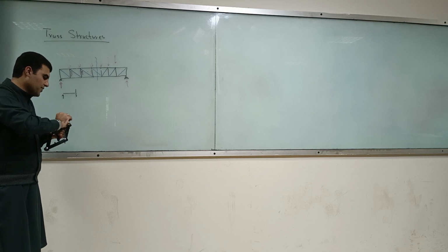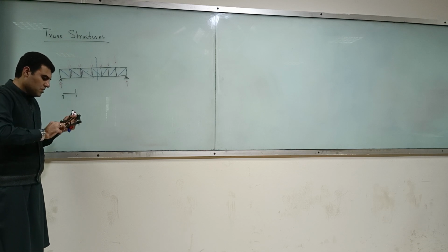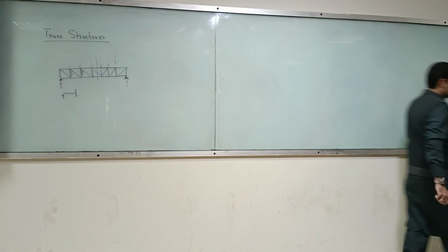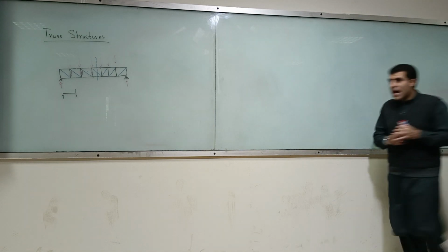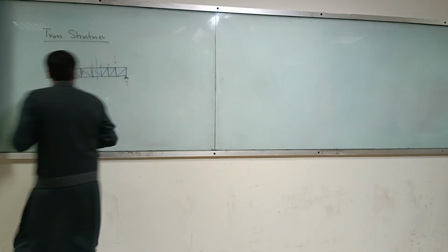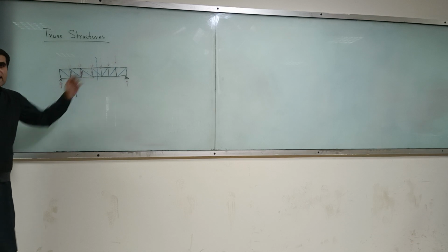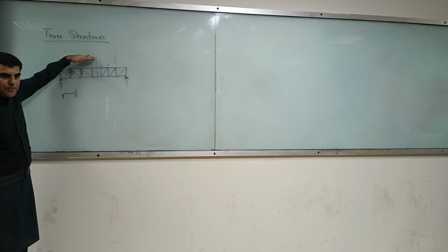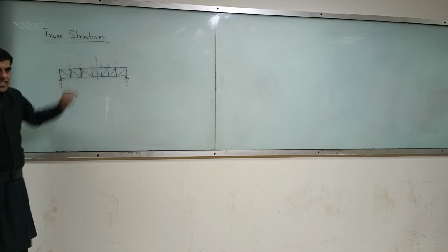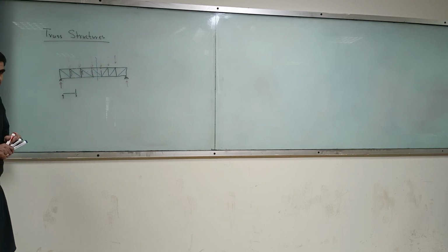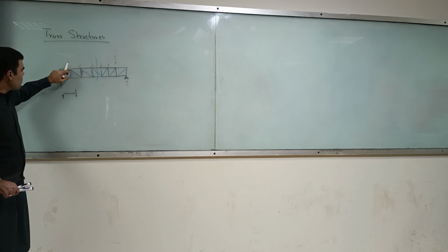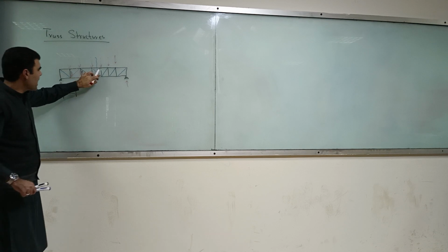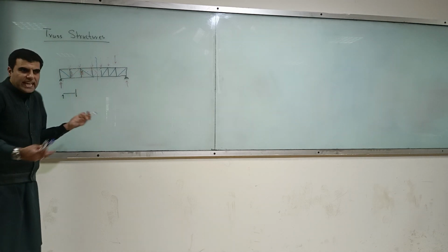So that is an important consideration. Now, in the case of earthquake, it's not necessary that load comes like this. You can have loads in this direction also. So what people do then is, you provide one like this, another one like this, one like this, another one like this, because steel can take some compression.